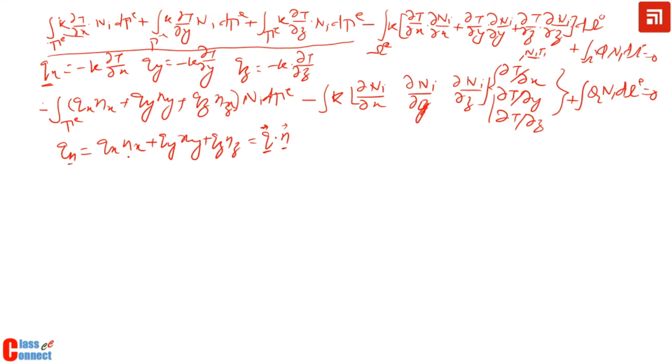So this heat flow can either be convective heat flow, or we can specify the heat at the boundary. So this particular term will have two components now. One is the heat convection component, and the other is the heat that we specify on the boundary, how much heat is being taken away or how much heat is being given into the surface of the element.